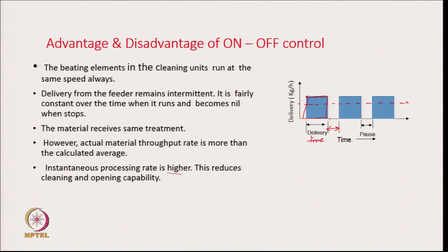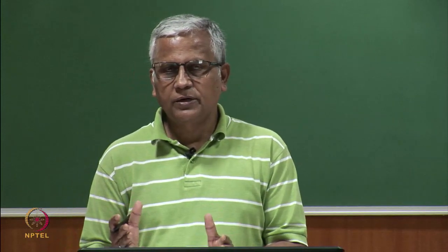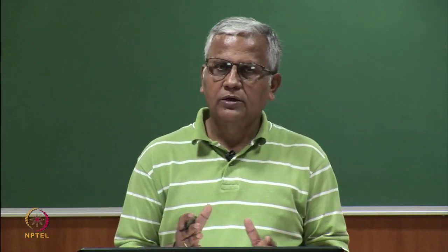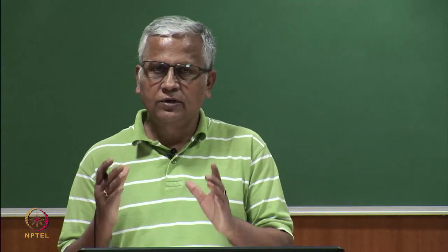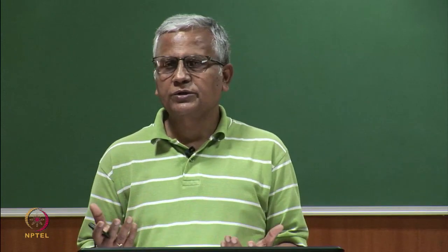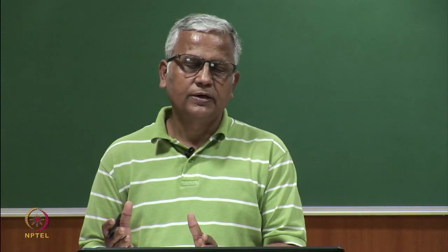and the opening capability of the machine is going to reduce, since I am feeding too much material over a certain period of time, and then for some period of time, even though the beater is running, it is idle, because it is not receiving any material within the chamber, and therefore, it is not really opening and cleaning the tufts. So, as long as I am not feeding any material to the particular opening and cleaning unit, even though the beater runs, it is not processing the material. So, when it runs, I am feeding more material, and sometimes I am not feeding any material.